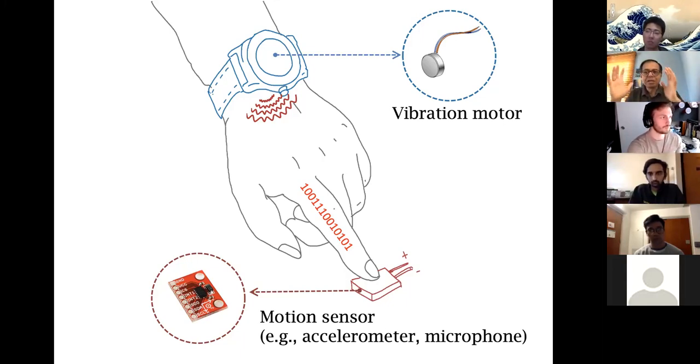And I take these frequencies and I now take an IFFT. Each frequency is like a sinusoid signal. I amplify the weights of each of these frequencies based on that 1, 0, 0, 1, 1, and then I take an IFFT of that. An IFFT of the frequencies will give me a time domain signal. Guys, are you with me? Now the time domain signal, I pass that as the current in the coil.